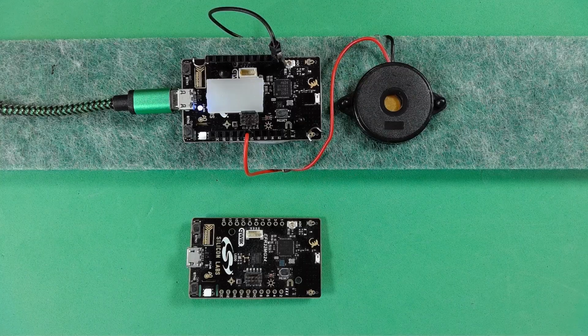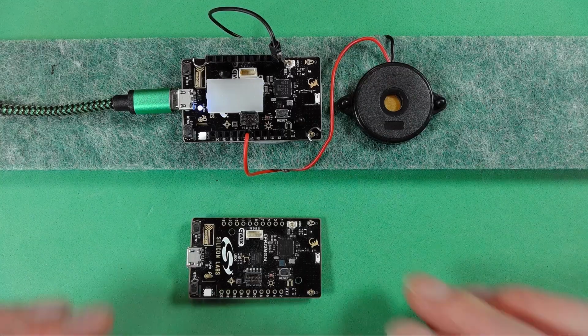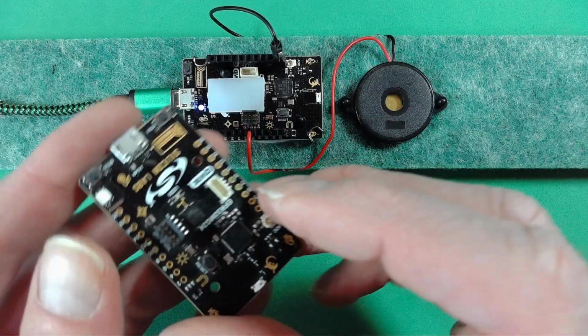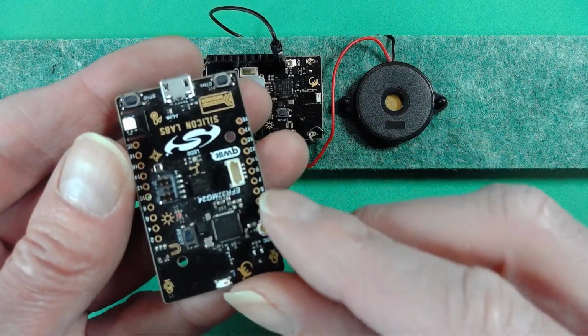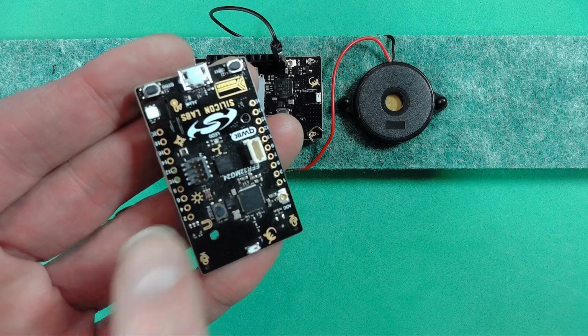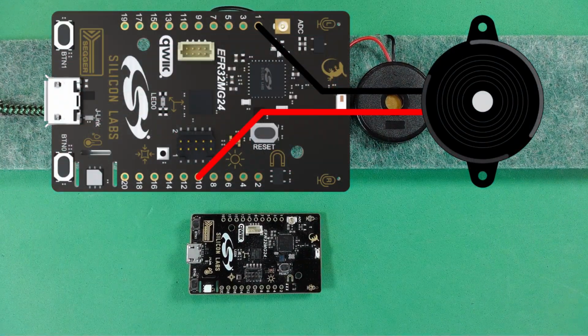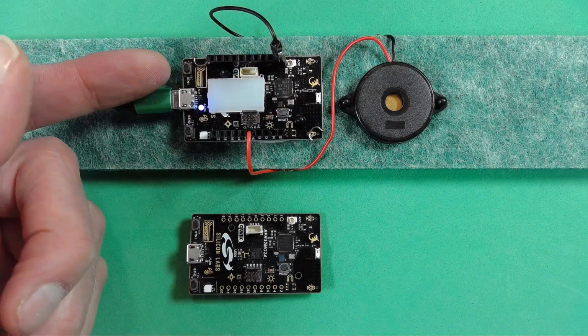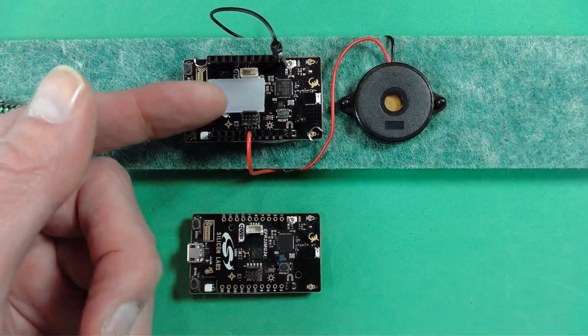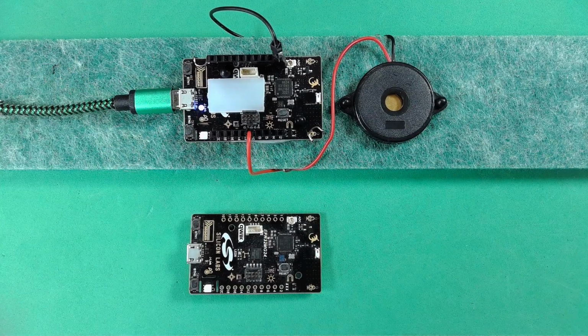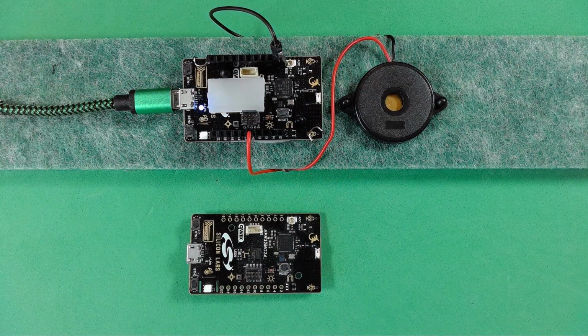The second board is the Silicon Labs XG24 Dev Kit. This board does not come with header sockets, but you can easily add some to the expansion holes on each side and connect the piezo buzzer to the ground on pin 1 and the GPIO on pin 10. Or you could solder it on directly. This board also has the 2 buttons used by the application and an RGB LED, and use is made of the red and blue channels here instead of 2 separate LEDs.